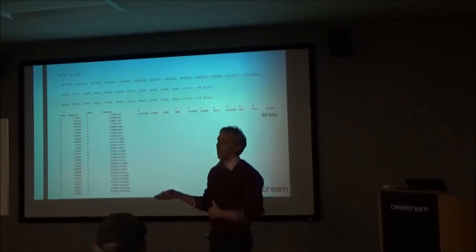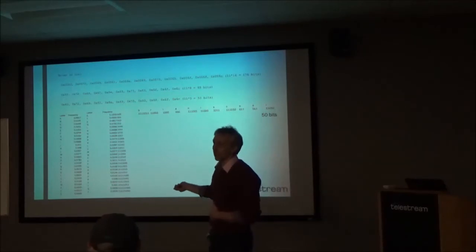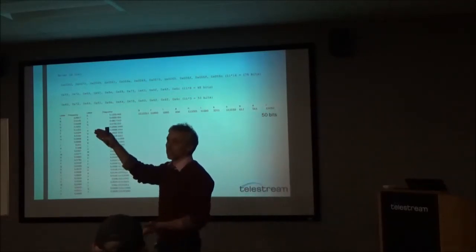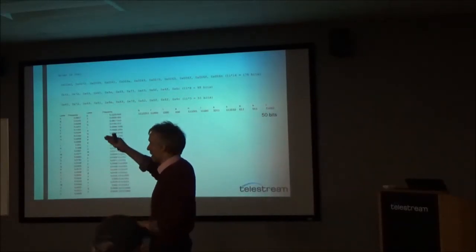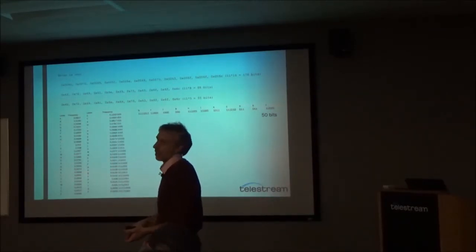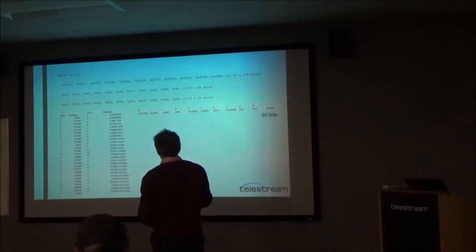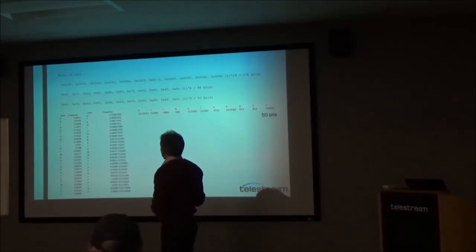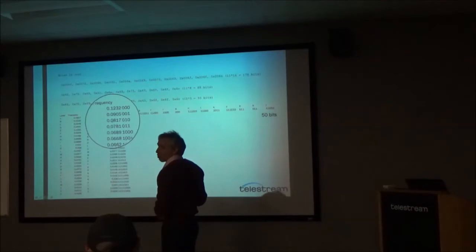Now there's lots of ways that you can derive this table. How do you take a distribution of symbols and assign a code to each one of those? This is the most simple way that I know how to do it, which is that the number of ones at the beginning of the string represent how many bits I'm going to use to transmit the rest of the number.